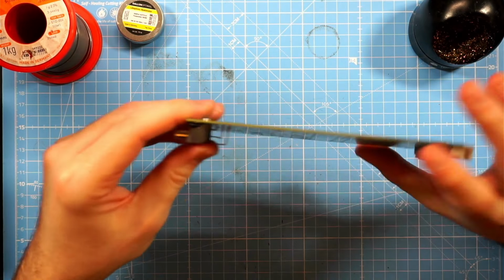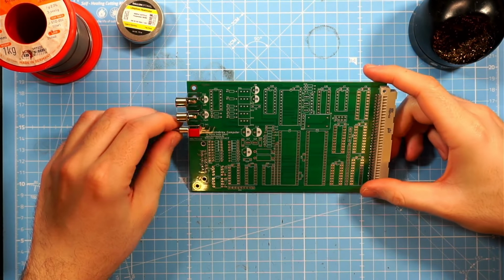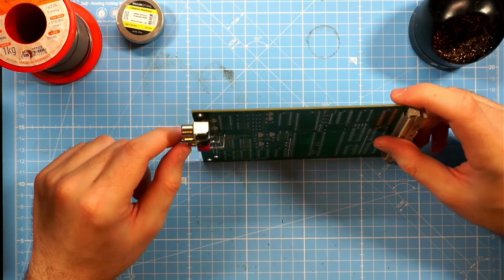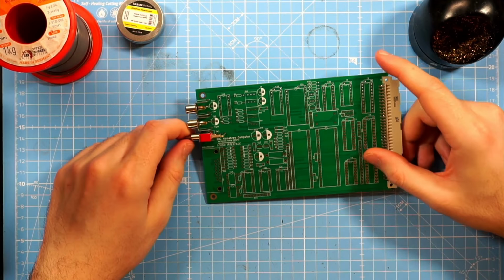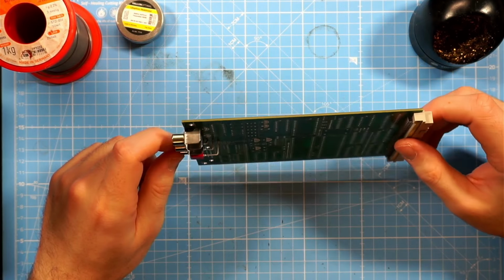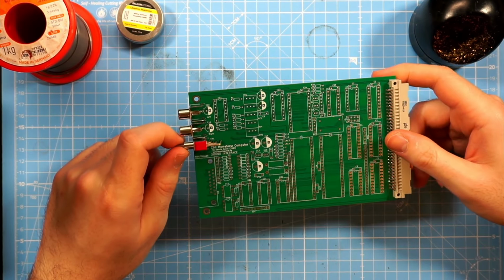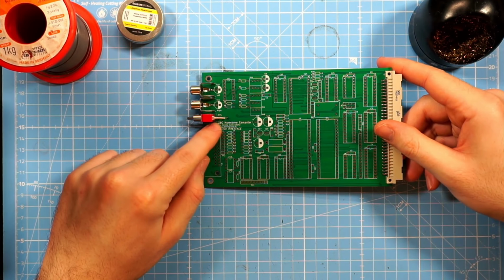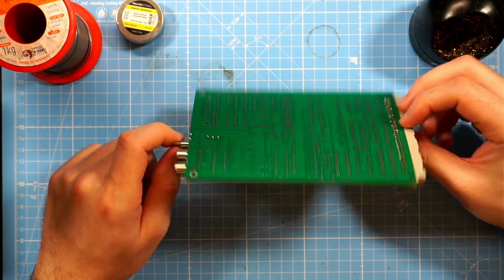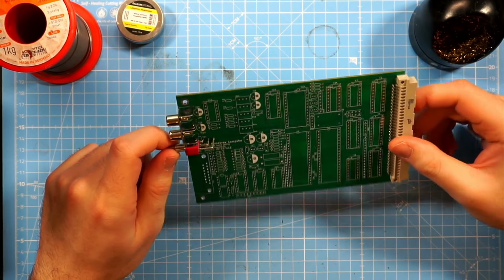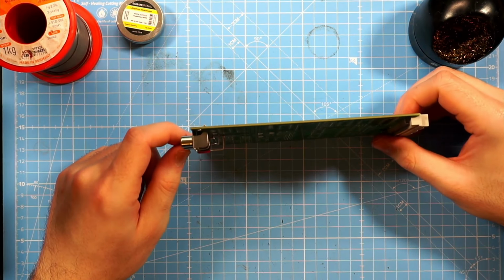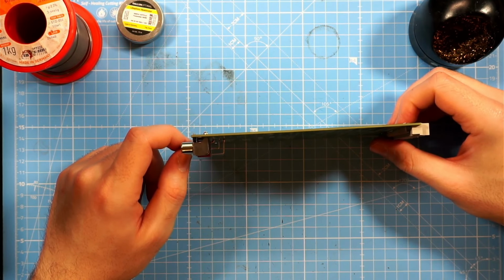I already did some stuff to this PCB. I've already added a switch and those two RCA jacks. The reason why I already added this is because I also got the footprints wrong. Well, technically they are at the correct position, but the diameter of the through holes were too small, and I had to do some modifications to the PCB and to the switch itself. Not too much of a problem because this is only stereo mono. It does not look beautiful if you look from the side, but it works.